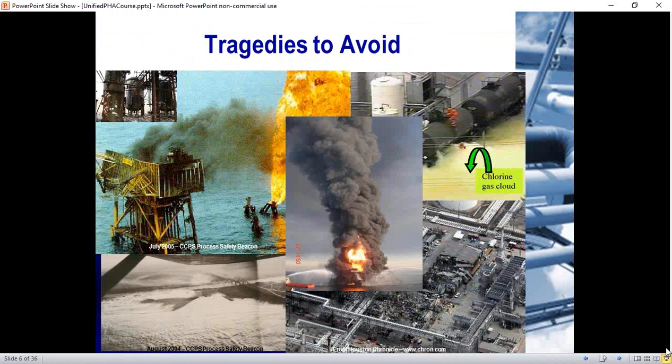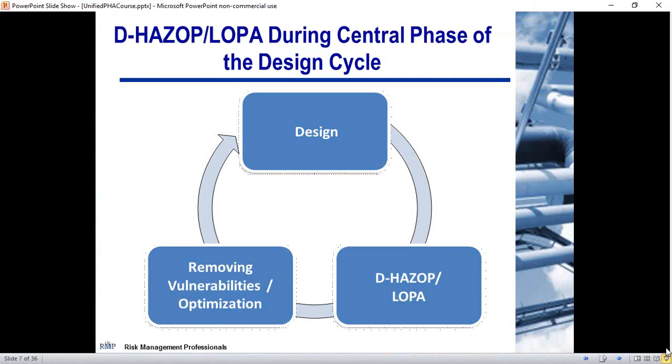But first, let's take a quick look at the design cycle. All right, basically it's pretty simple. You go ahead and partition the design, whether it's in-house personnel, if you're doing an open arts facility, or vendor packages. You do your design work, pull it together, then most of the designs nowadays are doing some form of safety assessment. Let's say you're doing a design HAZOP or LOPA.